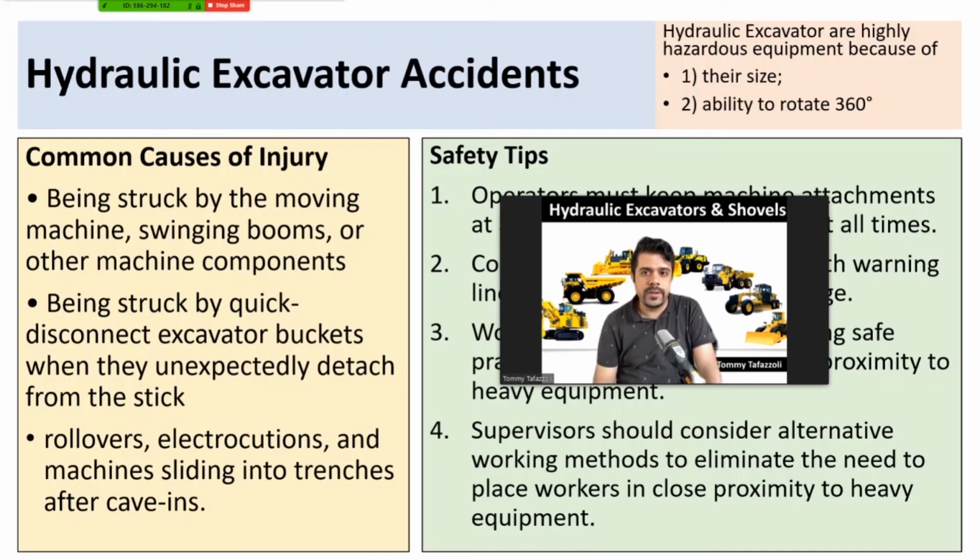So the excavator operator should have a good understanding about balancing the machine's load, because when the machine is in a diagonal situation, if you apply a lot of extra load on the heavier side, then there is a good chance of rollover. Okay, there's also a chance of electrocutions because the bucket sometimes could hit the power lines,